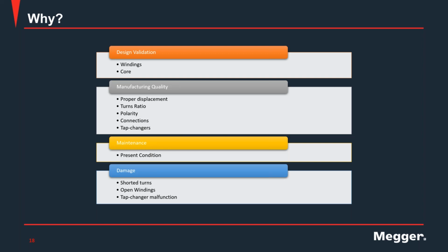We can assemble the windings or connect them in an incorrect way, and also, when constructing the necessary vector configuration of a Y or a delta, mistakes can be made during manufacturing. Insulation failure: when we have damage in the turn-to-turn insulation that will result in shorted windings, it will be reflected in the TTR results.